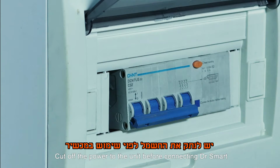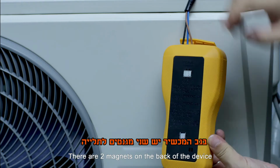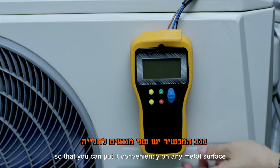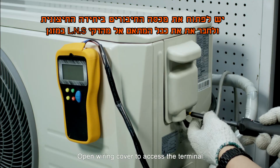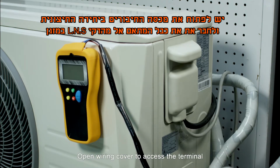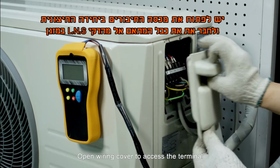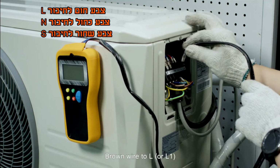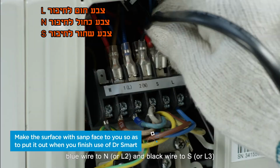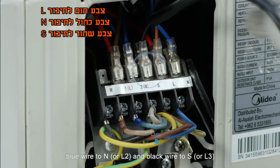Cut off the power to the unit before connecting Dr. Smart. There are 2 magnets on the back of the device so that you can put it conveniently on any metal surface. Open wiring cover to access the terminal. Connect the wires to the terminal according to the signs. Brown wire to L or L1, blue wire to N or L2, and black wire to S or L3.